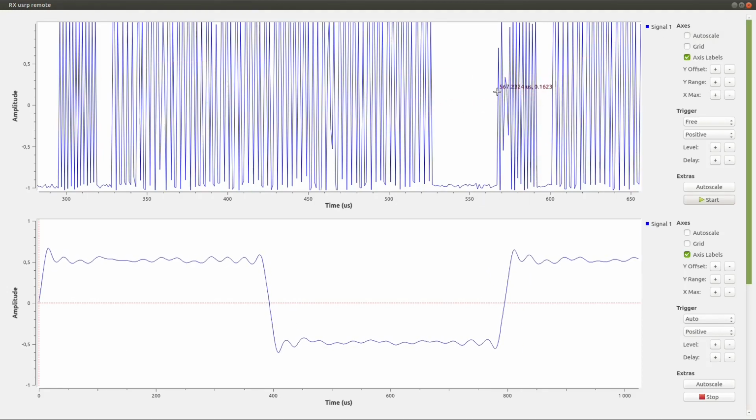But I see another problem in here, because I can clearly see that, for example, at this step, my signal has a spike drop in here. So maybe I should do something about that. It depends, but if I can decode at least one frame properly, it's not a problem. But I can clearly see that in here there will be some problems decoding the signal properly. So I will use a threshold in order to clean this signal a little bit.